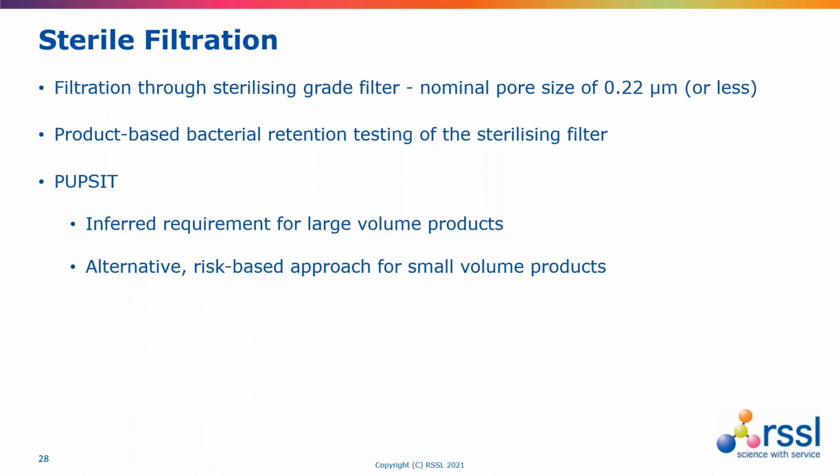For small volume products, it is permissible to go down a risk assessment route in lieu of PUPSIT. This does require having lots of detailed knowledge about the sterilisation process, the supply chain, the chance of filter failure, and so on. And there is no dropping of PUPSIT through any risk-based method for large volume products.